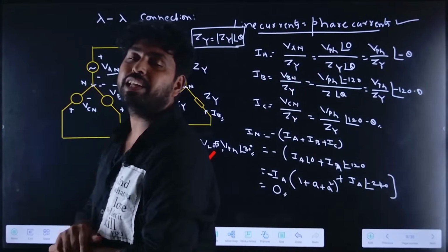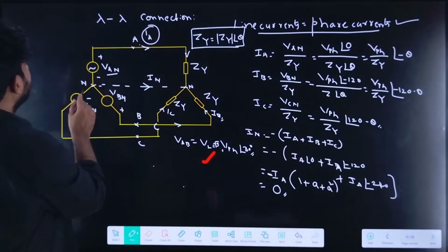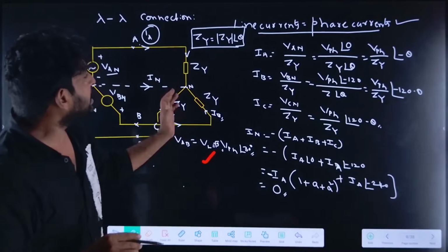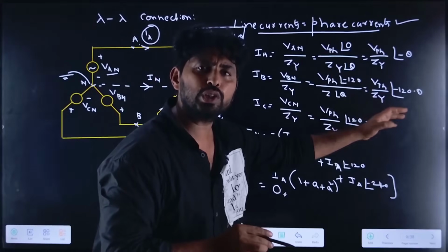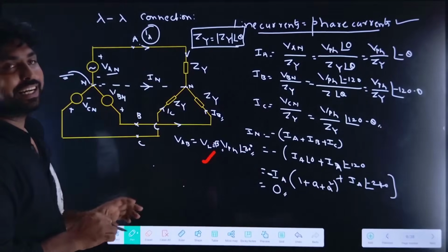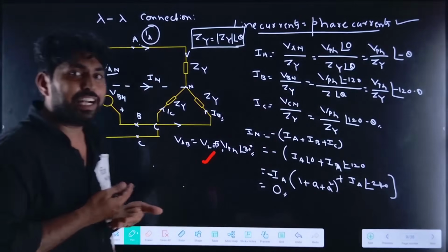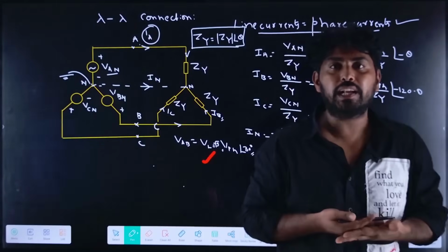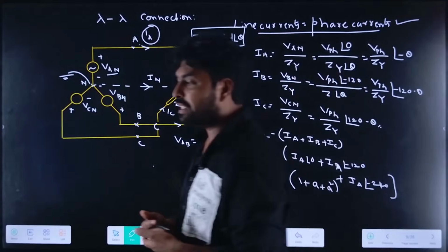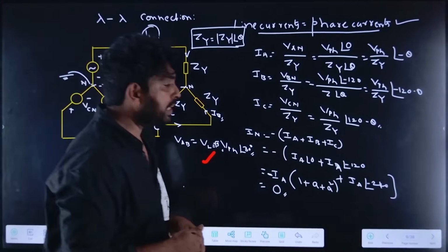So how can we avoid the floating of neutral? It can be avoided by earthing this neutral point, and the sub networks that are connected to the source are also earthed and interconnected. What happens? It makes the earth potential common, which is 0 potential, so it keeps the neutral point at a constant point. Generally, this problem occurs in distribution networks, right?